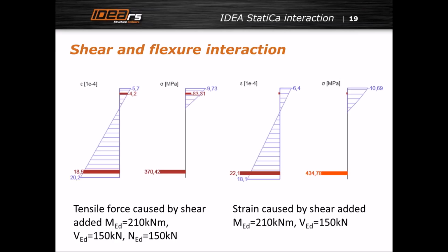It is added, or better said, the tensile capacity of the reinforcement is decreased by this strain, and the response of forces to normal force and bending moments is found. So it is like if we subtract this strain calculated for the acting shear force from the stress-strain relationship.